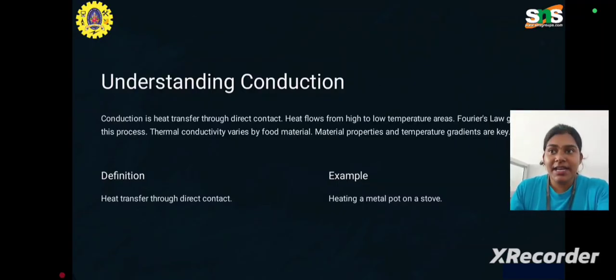So, the thermal conductivity varies significantly among different food materials and packaging materials, influencing how quickly the heat is transferred during the processing. So factors such as moisture content, density and composition affect the conduction rates. So understanding these properties is crucial to design the equipment and process that ensures even and efficient heating or cooling, which directly impacts the food safety, texture and flavor retention.